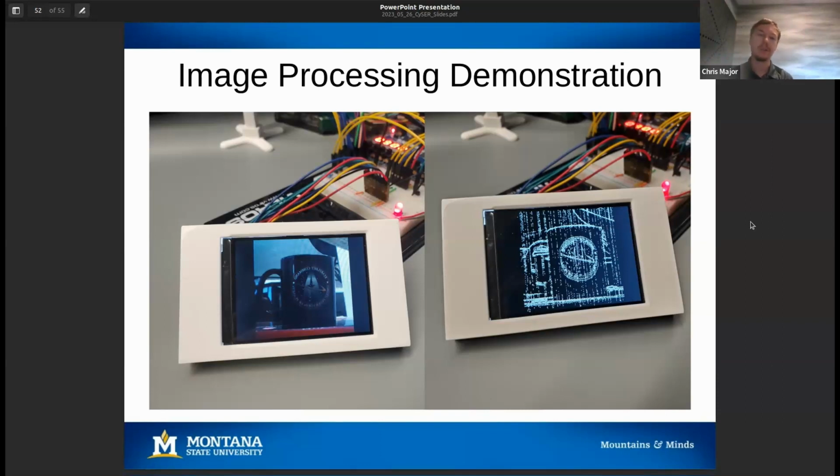So we created a system which would be able to take in raw image data from a basic camera, one of the OV modules, and then output that data to a screen. And then for our attack vector, we figured, let's go ahead and have a UART come in again, just as we did before, but we're going to do a basic operation on the image that's easily visible on the screen. And so we elected to do a basic edge detection, just a quick horizontal edge detection. So the idea here being that we have a system that's taking in sensor data, outputting it, and we have the perfect attack vector where someone could either flip the mode of the screen or perform a buffer overflow.